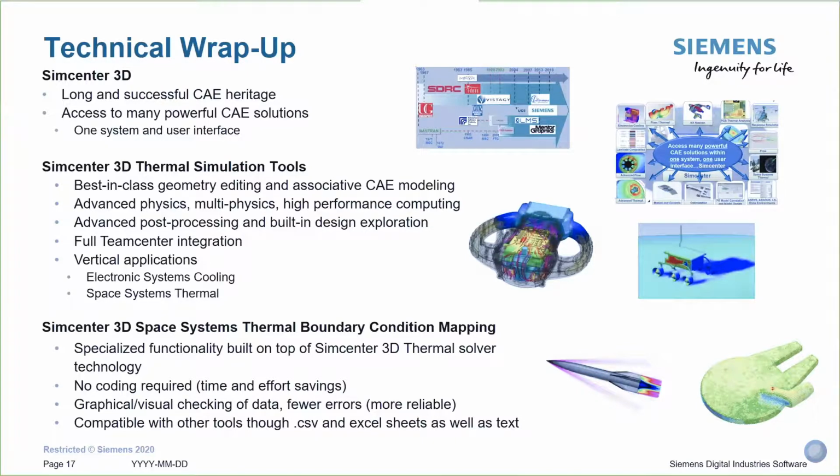We have advanced physics, advanced radiation models for orbital heating and solar heating, non-gray radiation, as well as ray tracing. We do have multi-physics capabilities, so for thermal and flow analysis. We do take advantage of high-performance computing, so you can run your view factor calculations as well as your thermal model in parallel.